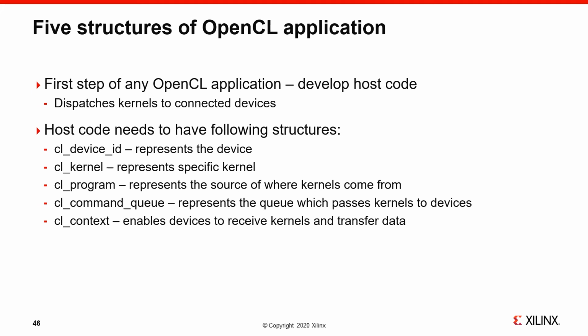CL kernel represents a specific kernel. The FPGA binary may have multiple kernels, which will all be available when the device is programmed. So the CL kernel allows us to differentiate between multiple kernels running on the same device.